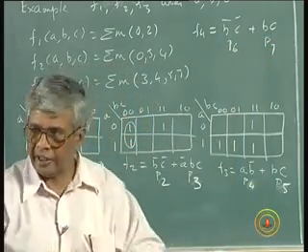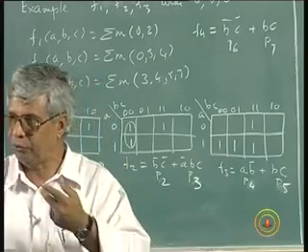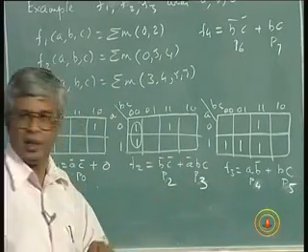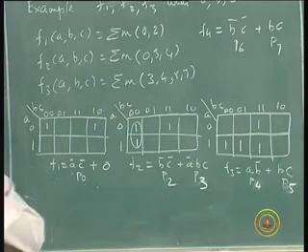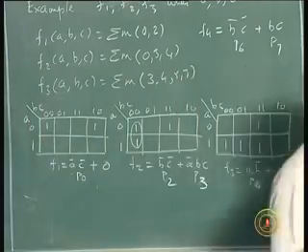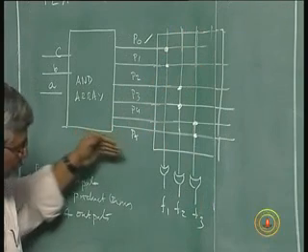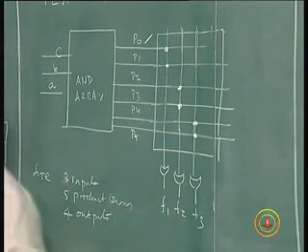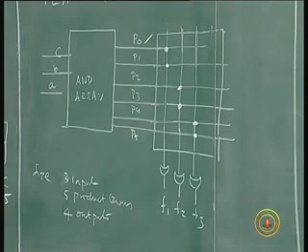and again generate P6 and P7, even though P2 and P5 are available. I cannot use them because I don't have these inputs tied to the next. So if I have a fourth AND gate, OR gate, with 2 inputs, those have to be again programmed for the same variables which are already there. Then it becomes less efficient beyond that.